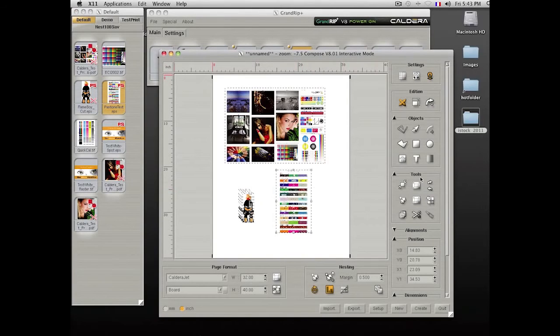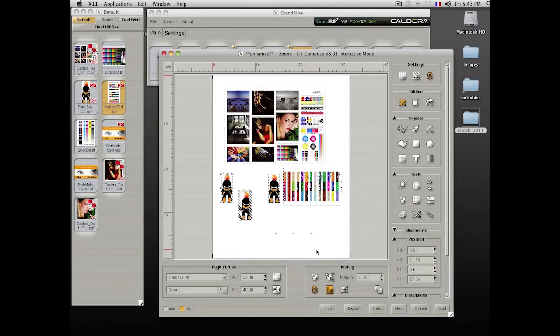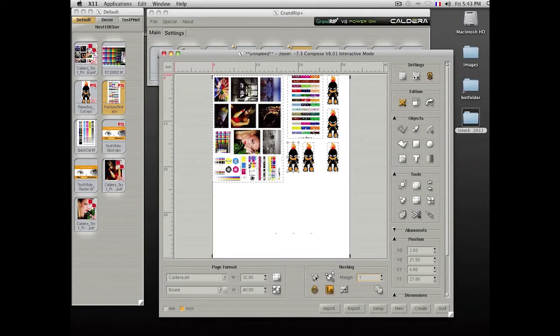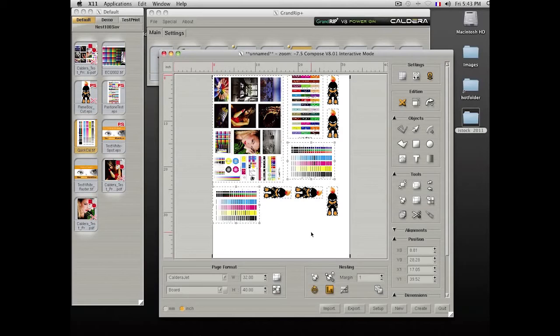For example, 5, and then place your files manually. This tool allows you to manually rotate or position files. You can also use a nesting mechanism and specify the space between 2 elements and hit the Nest button. If you need to add new files, you can do so by dragging them in and clicking on Nesting. You are able to nest files with all types of elements, for example, files containing cut contours, PDF files, raster files, JPEG files, RGB files, CMYK files, and files with different input profiles.